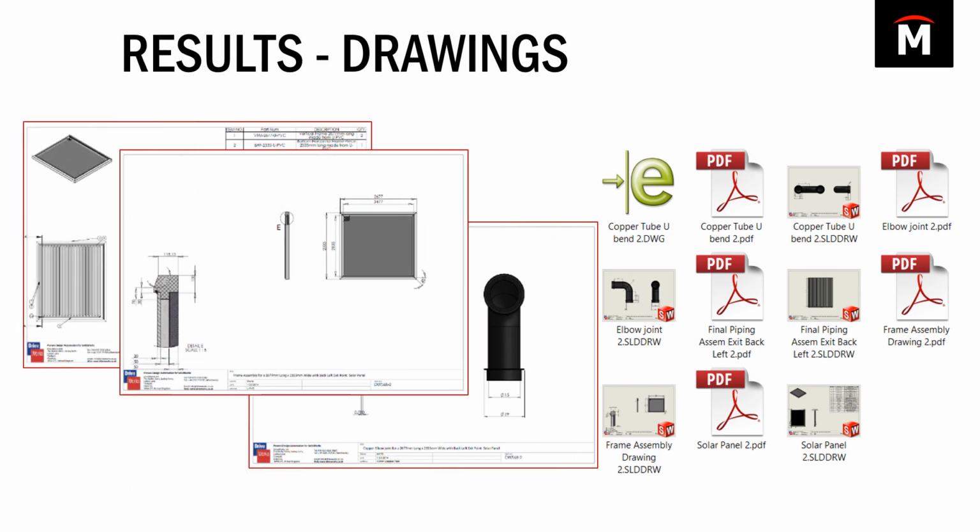Now once it's gone through and it's actually generated all of the parts and assemblies, it's going to start working on the drawings. What it can do with drawings, it creates all your SOLIDWORKS drawings. It can resize and rescale the views. It can reposition those views, drive annotations, dimensions. It can drive into your title block. And so the ultimate goal with Driveworks is to have it automatically create those drawings to where you don't even have to open up those drawings and modify them. They're ready to be sent to production so that your shop can start making those products.